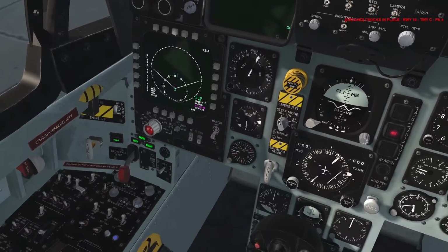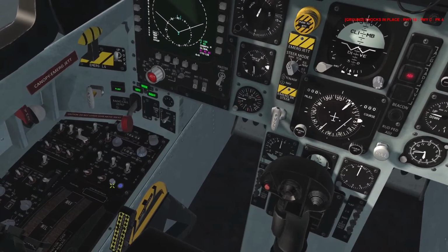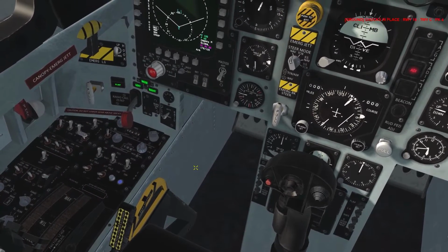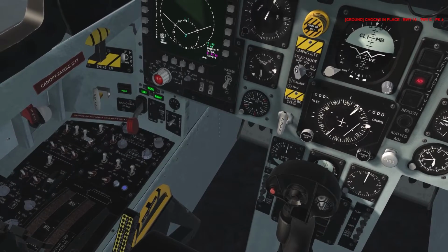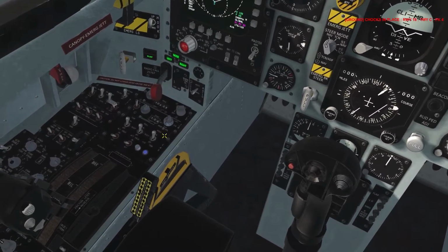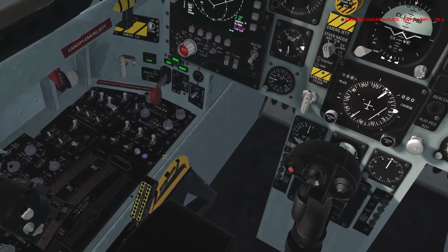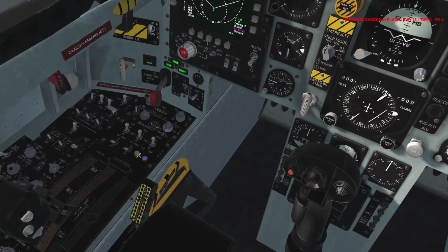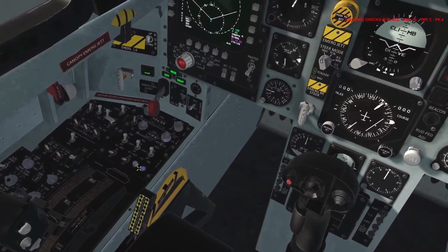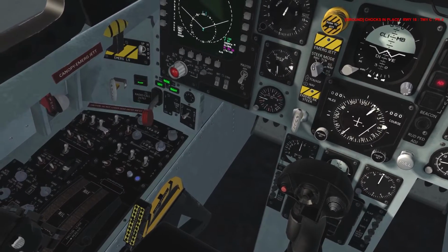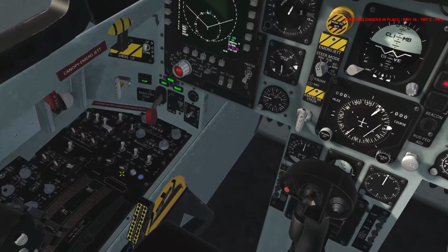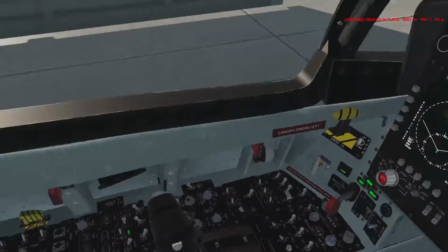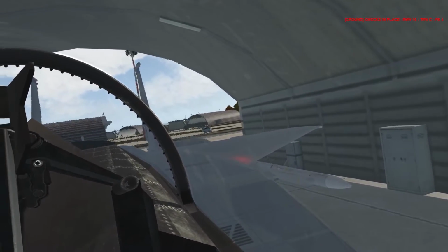Trim, so this is actually an item that I would recommend setting a keybind for, because this is the takeoff trim button, but it's not implemented yet. There is a binding that you can set for reset trim, because presently there's no way to detect if you have input an improper trim setting. So typically before takeoff you would depress that button to set the takeoff trim, and that would zero out any improper trims that you might have inadvertently input, but we don't have that functional yet, so strongly recommend setting a trim reset button. So flight controls, check. That's a good check.